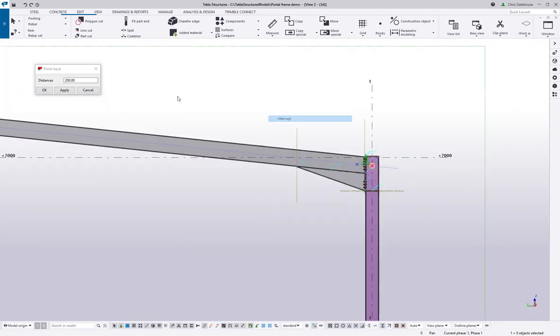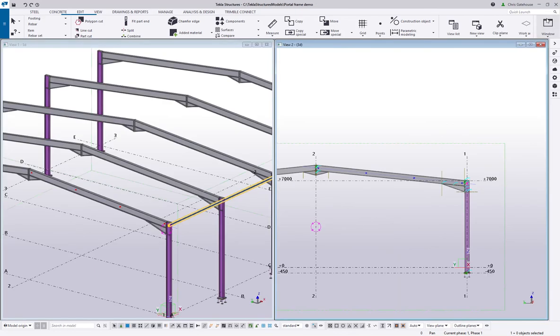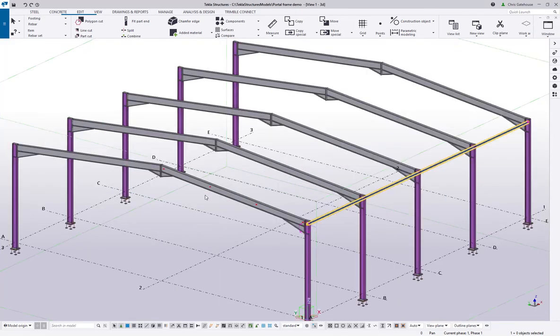And I'm going to want then sort of 3 braces. So if I go back into here, I can say create 2 points. Let's create 2 points along here. So that's my even spacing for my bracing. And I'm going to want to bring this up from there. So I will move these 2 points over to the next bay. So that's giving me my bracing setting out now.